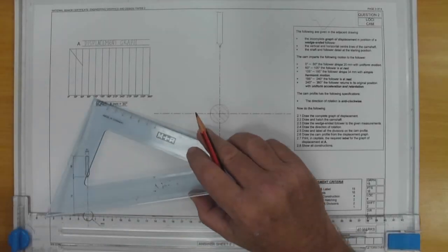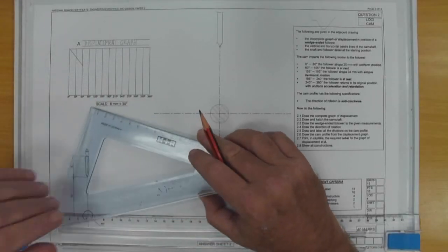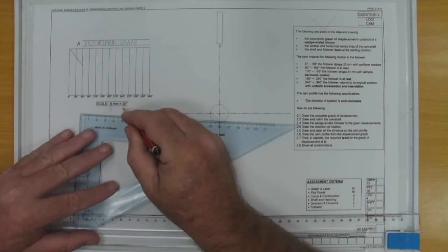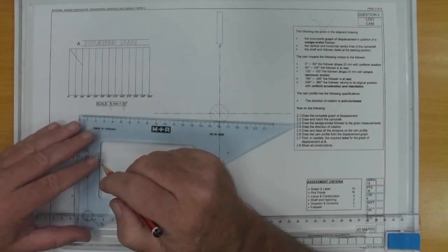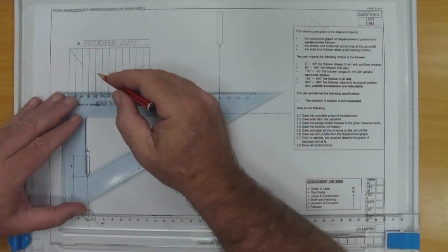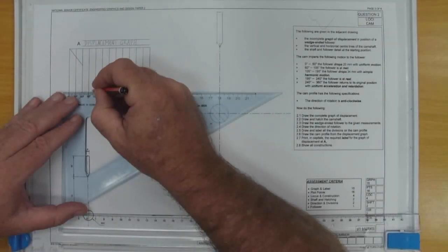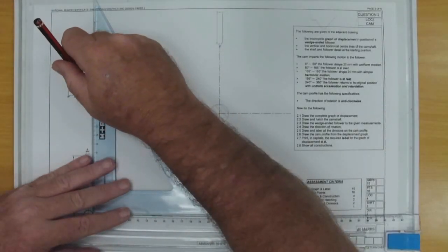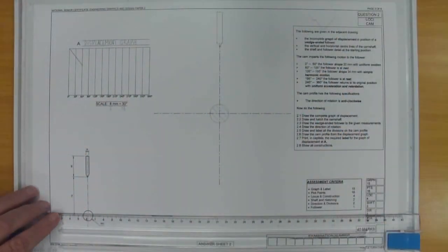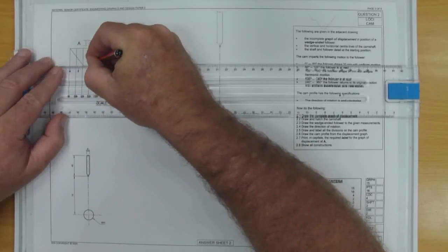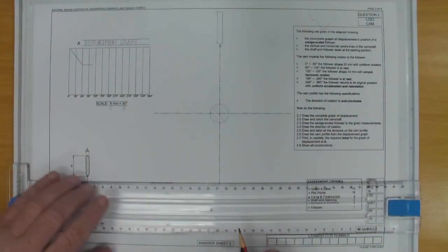Our divisions are 30, so we need to find half of 30, which is 15, and if we divide our scale here, that would mean 4 for every 15 degrees. So I need to now find 4 millimeters away from 90. Put that little line in, and here is that dwell period where the follower isn't doing anything.